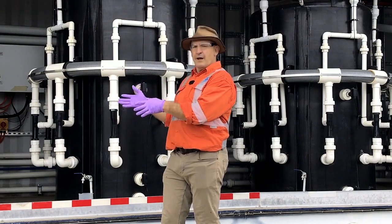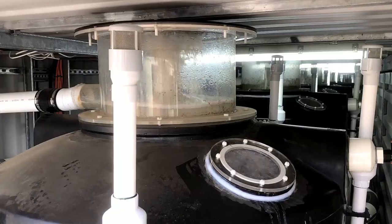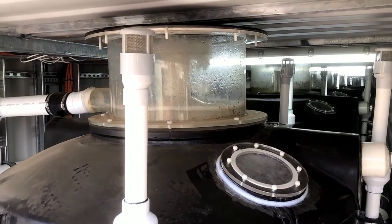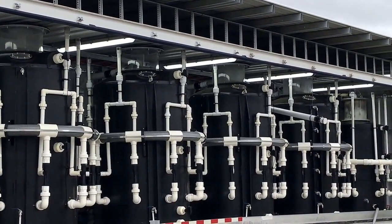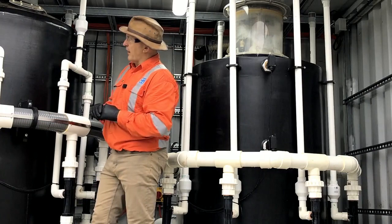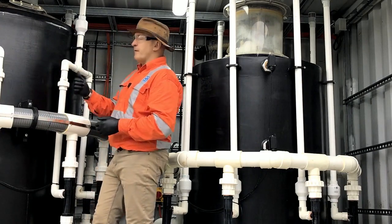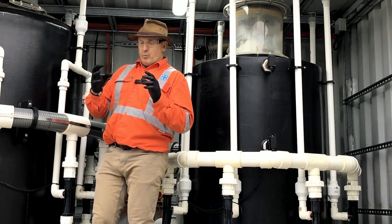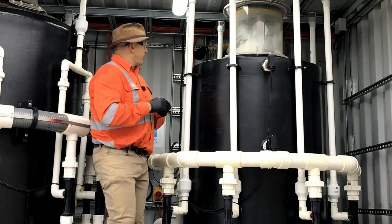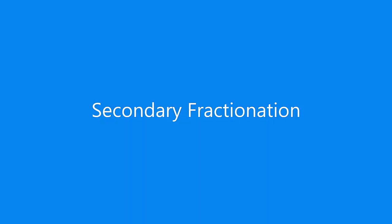The treated water, all of the long chain compounds essentially are removed at this stage, and a large proportion of the shorter chains. Every litre of water only goes through one of these. They don't pass from one to the next. It's just each one of them treats its water. The wet cut comes off. It accumulates in a vessel around the back here. And that wet foamate is then delivered to the secondary fractionator.